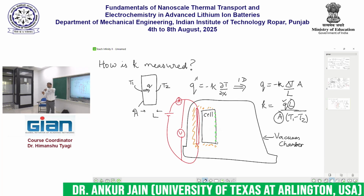Each thermocouple comes with two wires, right? So you're asking to have a large number of wires. Each of these wires will need to go out of the vacuum chamber, right? So you need to make sure that you have space available to pull all of these wires out. Each of these wires will likely break the vacuum. You'll have to seal it up effectively and all that stuff. What about on the other side? On the other side, we also need thermocouples, probably, right?